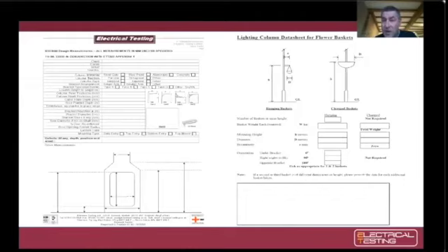You then need to provide us information with regards to the attachment, obviously the number of attachments, the weight of the attachments. This one is a hanging basket, so we need to know the weight of it when it's watered as well, and your desired mounting heights too. So like I said, this information is collated, it's combined, it goes through the process of the design, and then we get an outcome in a report.